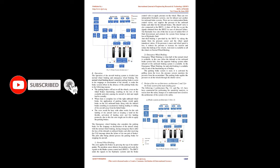The emergency wheel braking also considers the parking brake for the stoppage or deceleration of the aircraft along with the normal wheel braking, during emergency, that is after the loss of the inboard or outboard brakes and after receiving the COM message about the failure of one pair of brakes. The pilot, after being alerted, presses the parking brake for stopping the aircraft.